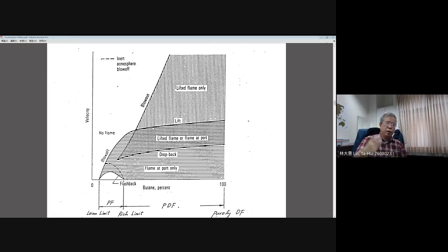There is an additional influence coming from the diffusion flame. This outer diffusion flame extends the limit of blow-off to experience higher injection velocity. And this solid line and the dotted, broken line have different features based on the oxygen available on the downstream side.